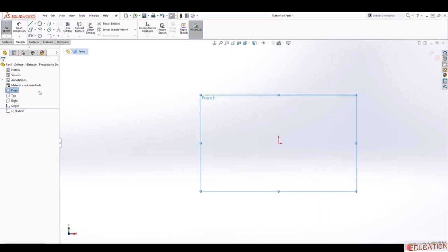In this lesson, we are going to be learning how to draw the rectangle. To start, let's just pick any plane. We can pick the front plane again and click sketch. Again, you will know you are in the sketch mode when you see the exit sketch up here, this red gizmo down here and this in the upper right hand corner. To draw a rectangle, we'll start from the first rectangle, which is a corner rectangle.